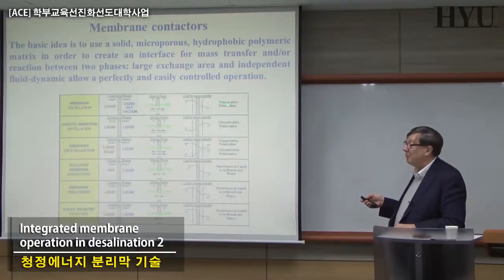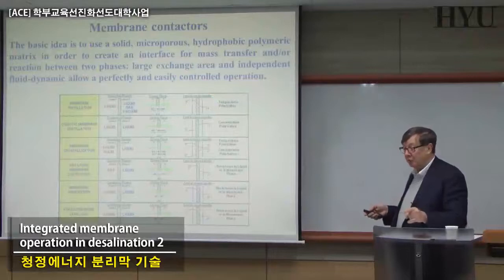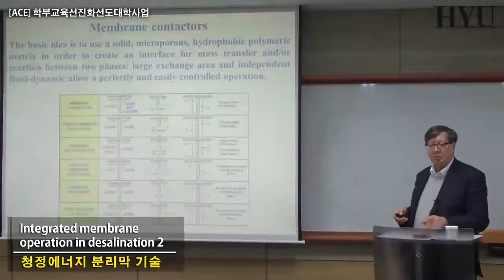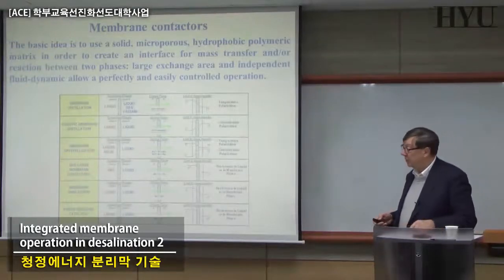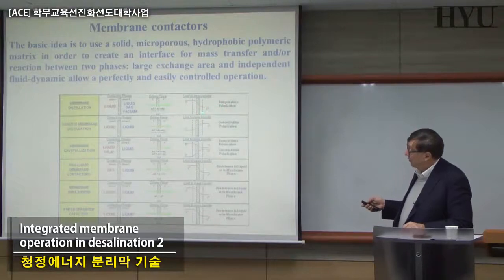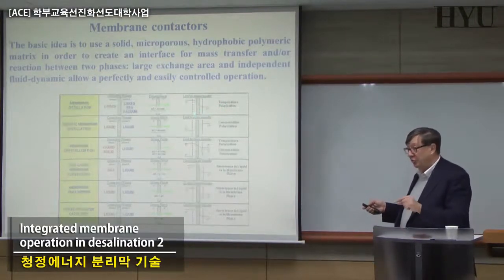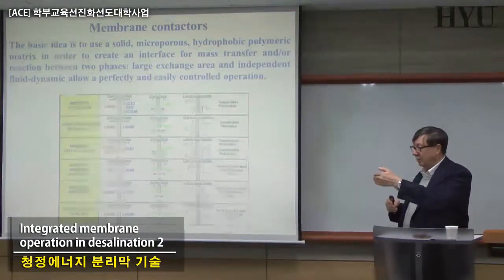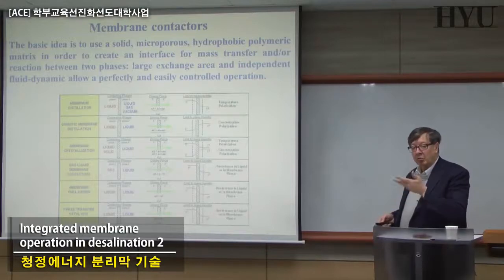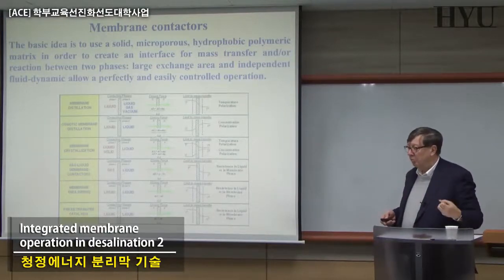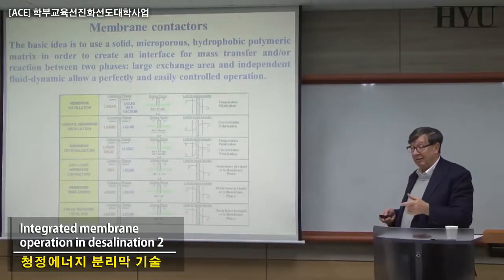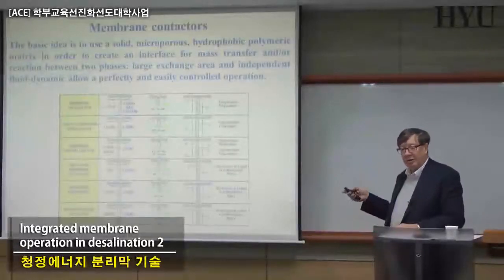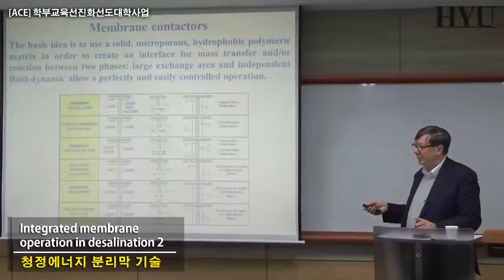What you can find is temperature polarization, however, which has to be controlled. And sometimes temperature polarization is more complicated and more difficult to control than concentration polarization. That is also a consequence of the fact that concentration polarization is not very effective. You don't have a convective flux to the membrane surface, which means in principle we don't accumulate a lot of species on the membrane surface creating fouling. So traditional fouling is much less severe in all these membrane contactors than normal.